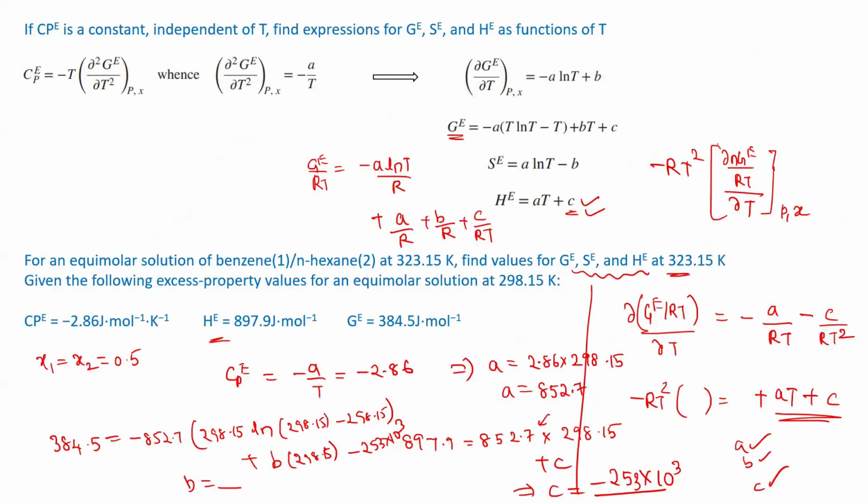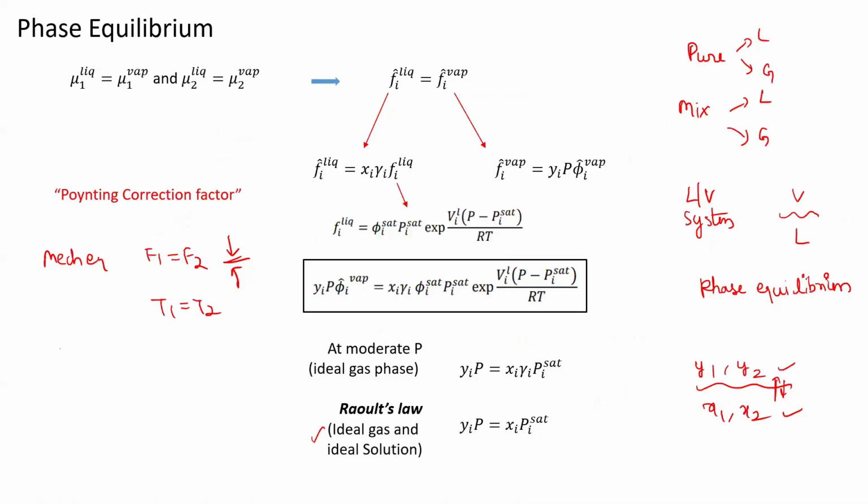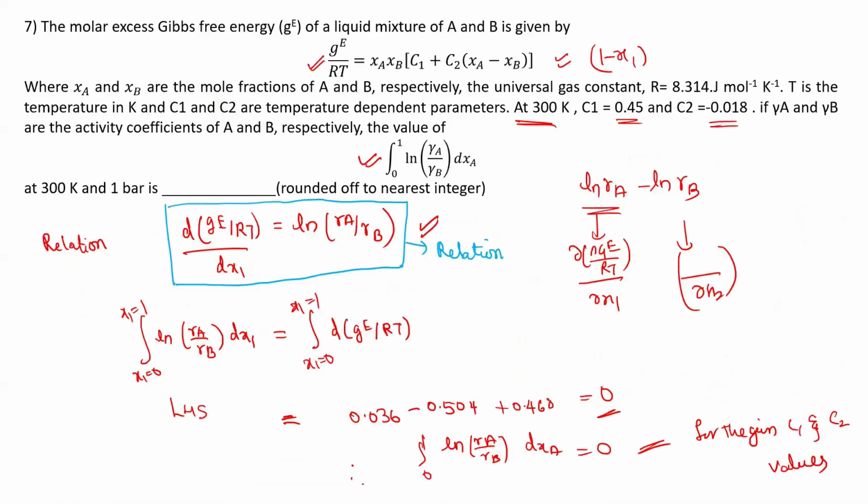As a part of this, there is a set of questions where you have either the temperature or the pressure of a system, and one of the mole fractions of gas or liquid, and with the set of equations we have, we solve them and find the bubble temperature or dew temperature, or the other way, bubble pressure or dew pressure.